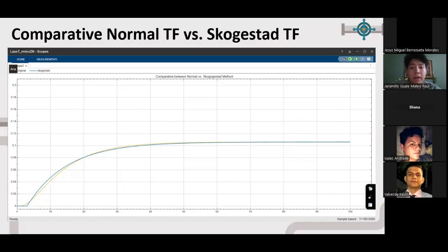Also, we identify that the small difference is in the initial dynamics because the reduced model rises a bit slower at the beginning, but then it matches well with the behavior of the complete model. This confirms that the order reduction is a good approximation since it keeps the main dynamic characteristics of the system, making the PID controller tuning easier without losing accuracy in the overall behavior.